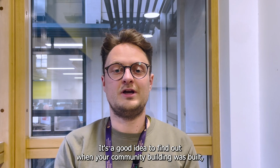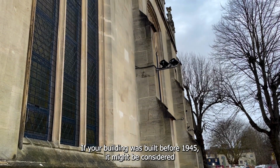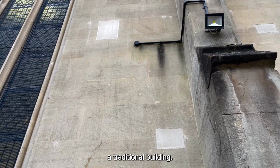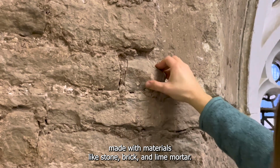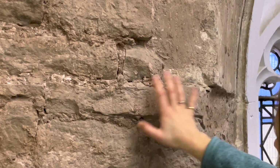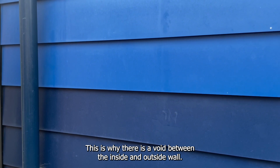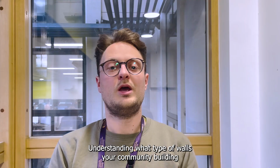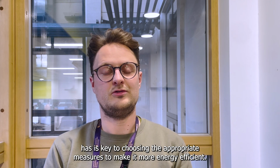It's a good idea to find out when your community building was built, as this can give you a lot of information about its construction. If your building was built before 1945, it might be considered a traditional building. If so, it's likely to have solid walls made with materials like stone, brick, and lime mortar. If your community building is more modern, it may have cavity walls. This is where there is a void between the inside and outside wall. Understanding what type of walls your community building has is key to choosing the appropriate measures to make it more energy efficient.